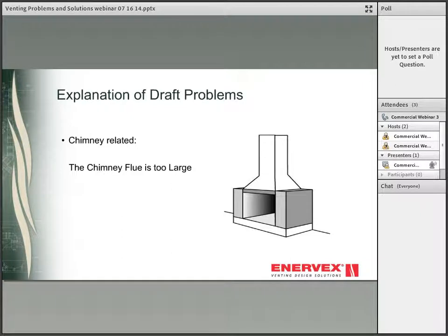While increasing the flue size increases the capacity of a chimney, it can potentially reduce the available draft. Gases move more slowly in a large flue, and a large flue has more thermal mass and more surface area than a smaller flue. More heat is transferred from the flue gas to the chimney and the chimney walls, which adversely affects the draft. This occurs when a stove or fireplace insert is connected into an existing chimney that previously served a wood-burning fireplace.